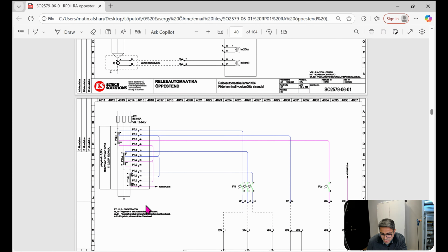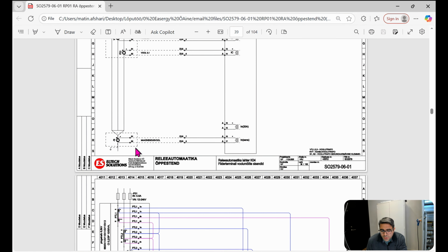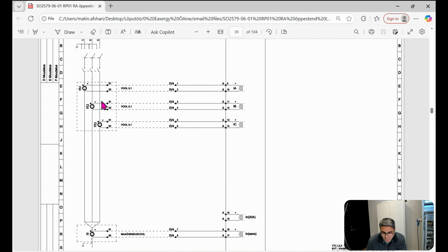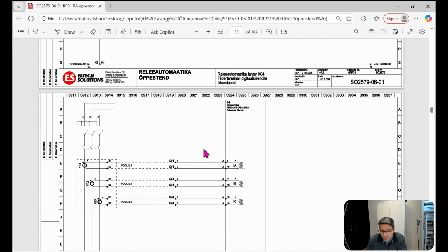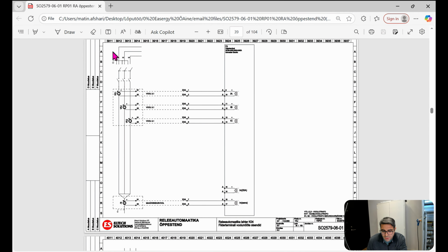In Estonian, pinge trafo, you see. So the CT's job is to scale down the current. If we have 100 amperes here, for example, and the ratio of the CT is 100 to 1, it will give us 1 amp. If here is 200 amps, it will give us 2 amps. This power transmission side we don't have in the lab. We have only our cabin that has the relay.